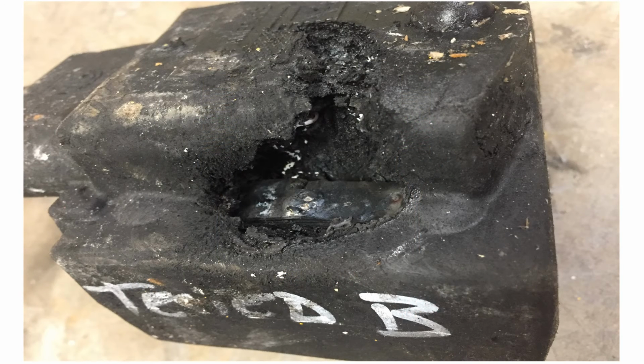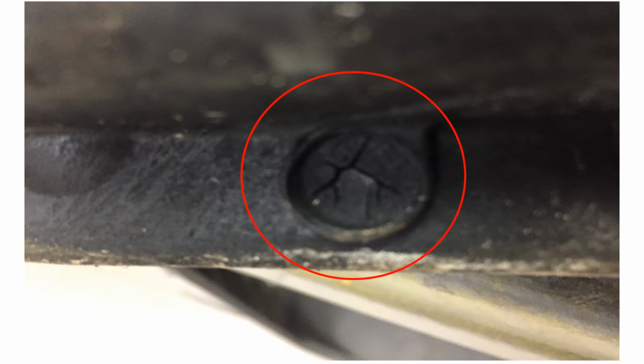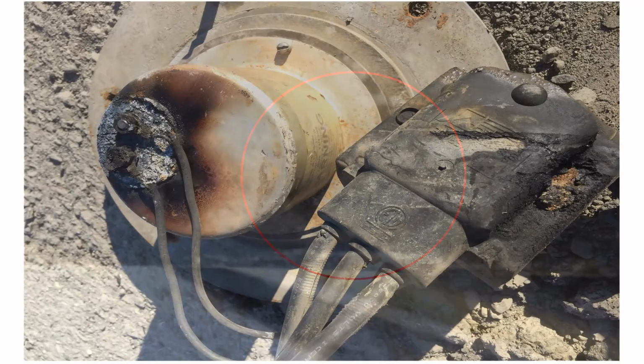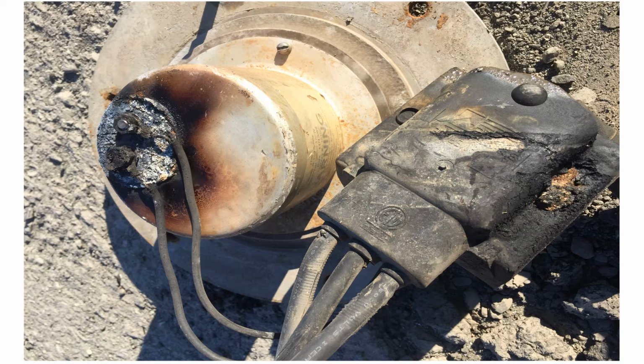So sometimes these faults are very obvious. Sometimes the signs of the fault are not very obvious, and quite often there are no visible signs on the exterior of the transformer at all. Regardless of how much physical damage there is to that transformer, the result is high voltage going to the fixture. This is very dangerous. If you were to pull this fixture with the power on, it's very likely you would be electrocuted.